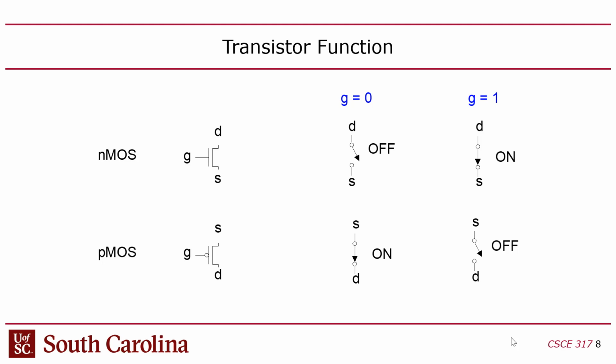So just to put everything in perspective, this guy is what's discharging the capacitors on the output of the gate. You want to turn this guy on, and the current is going to roar back into the gate. You might say, well, it's an output, right? Yeah, even though it's an output, really you're sinking current. You're discharging the gate capacitance of the gates that you're driving through this guy down to ground. So you're discharging whoever's depending on me through my drain here.